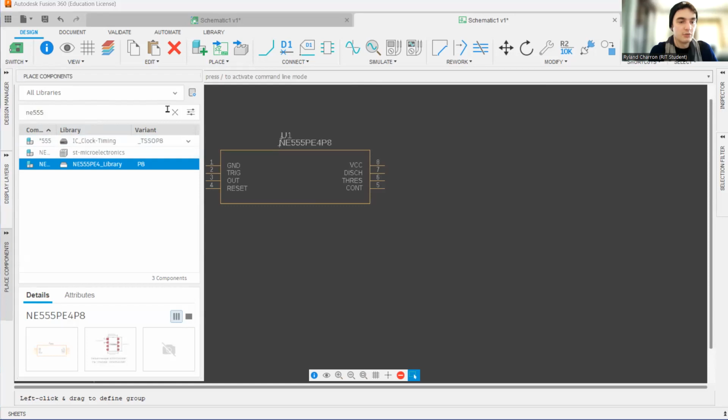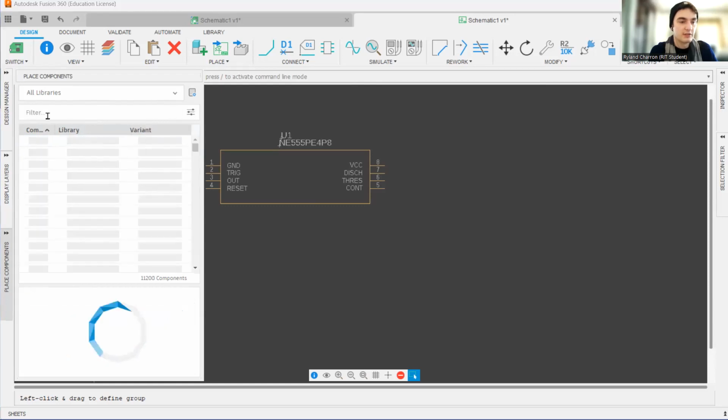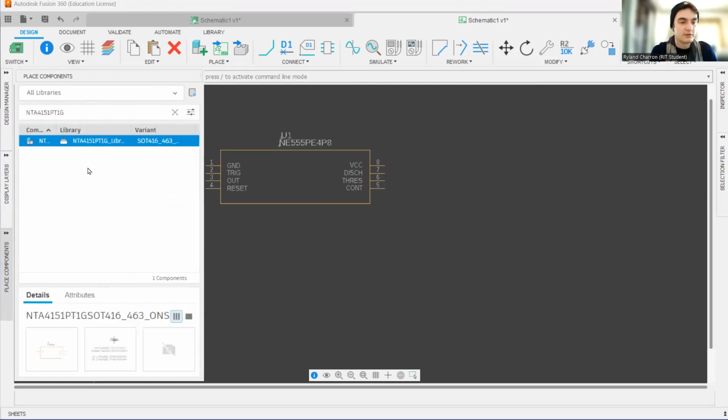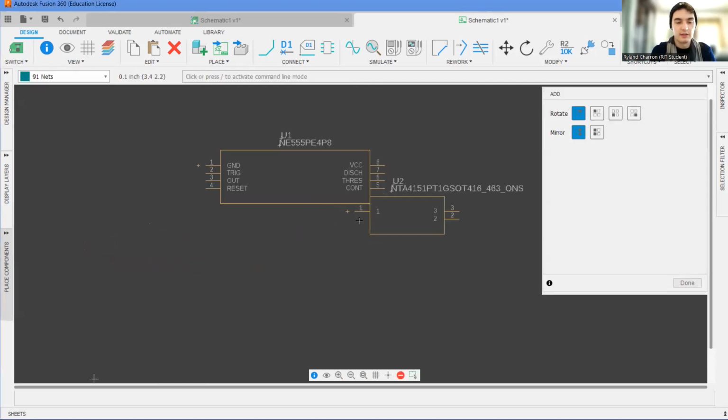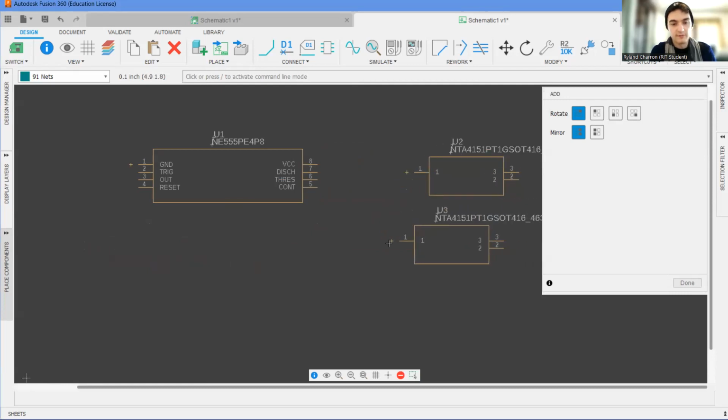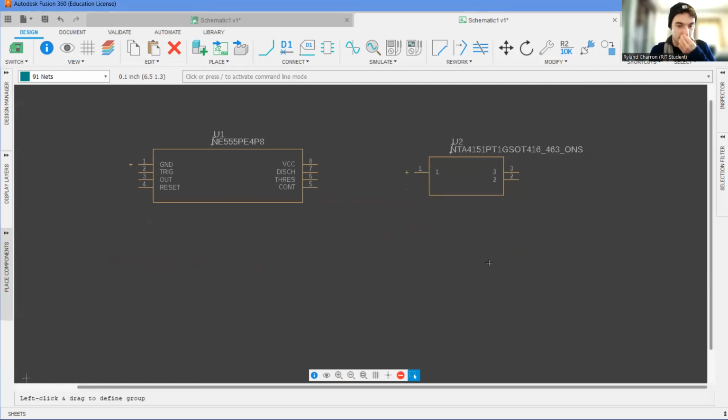All right, all libraries. So we're searching the whole device. Just gonna pop that in. There it is. There's the library. Double click. And there's the symbol. And we're just gonna drop that right there for now. Only need one, so I can hit escape and close the menu.